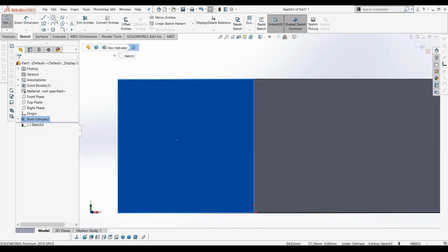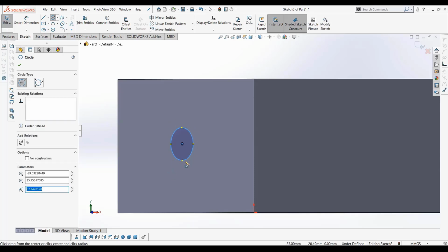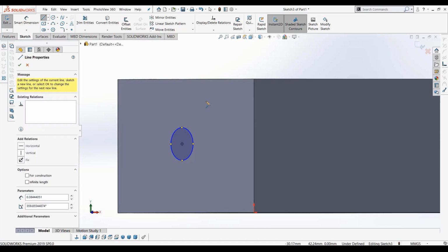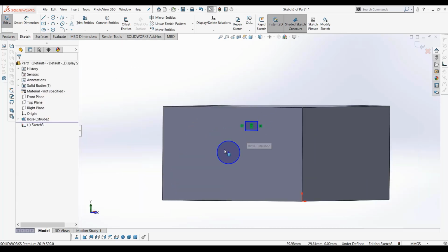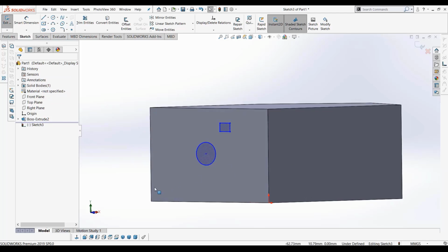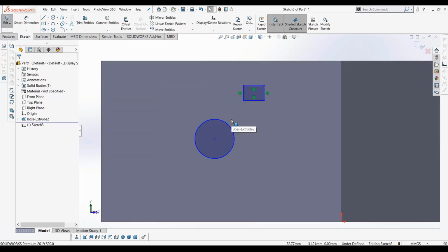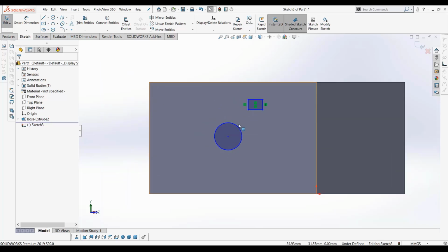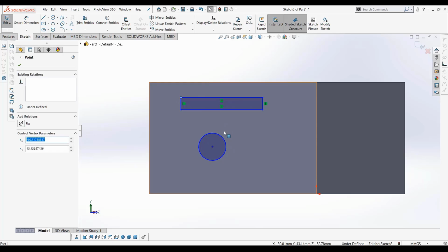Look, for example, I just gave it a slight angle, and now I want to draw a circle. Why did this circle become oval? Or if I wanted to draw a square like this, I see that it actually turned into a rectangle. To avoid this optical illusion, let's use the normal tool to bring this workspace right in front of our eyes, so we can easily sketch. Now let's assume we wanted to draw something like this, and we did. For now, we won't give it a specific size.